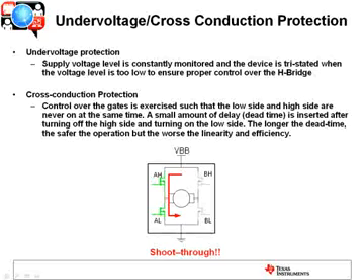The longer the dead time, the safer, more robust the operation. You just got more and more guard band. But as you insert more and more dead time, the linearity and efficiency start to get worse. So there's a trade-off there. You've got to make the right choice there in terms of safe operation versus linearity and efficiency. But that's all handled by the gate driver.